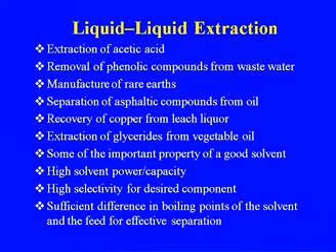Some of the important properties for a good solvent, because the choice of the solvent is also very important: high solvent power capacity, high selectivity for the desired component, and sufficient difference in the boiling points of the solvent and the feed, because you will have to strip the solvent from the product, and the separation will only be possible when there is sufficient difference in the boiling points.